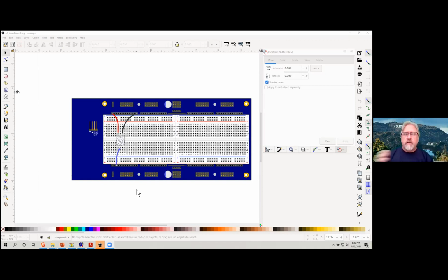So let's say, for example, I was using pin 15 and 16. In one cog, 15 was transmit. In the other cog, 15 was receive. So I could talk between the cogs directly through the 2 pins. You can do that if you're using software serial. You can't do that if you're using smart pins, because the smart pins exist in the pin and not within the cog.